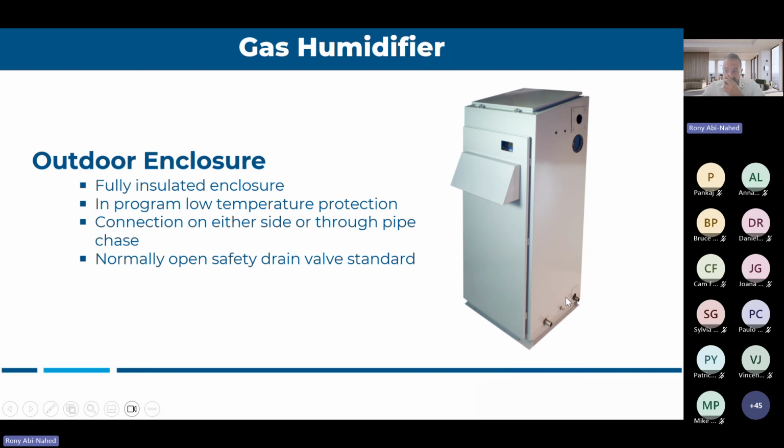Some of them will have heaters inside the enclosure, so you're always heating the tank so you don't freeze it. Some others will keep the water inside your tank at a higher temperature, even if you don't need humidification. So it heats the whole enclosure, and you definitely need to heat trace every single component that's outside the unit. Anything coming from the roof to the unit should always be heat traced.